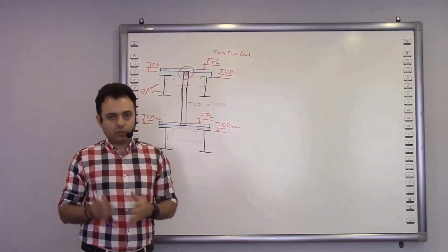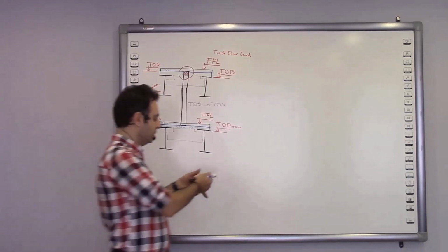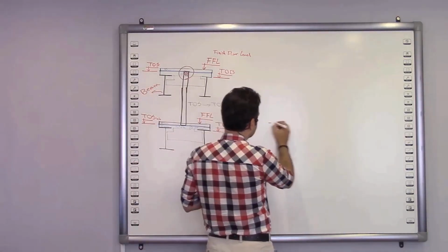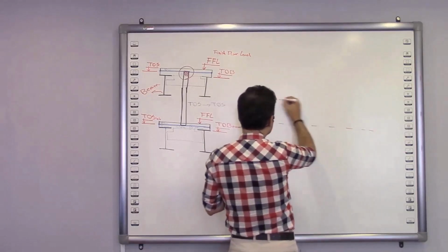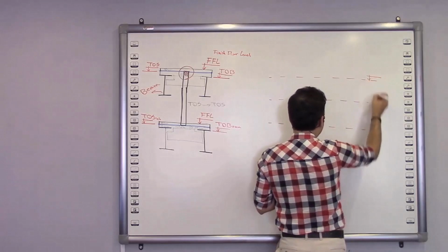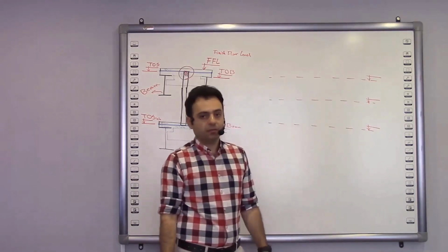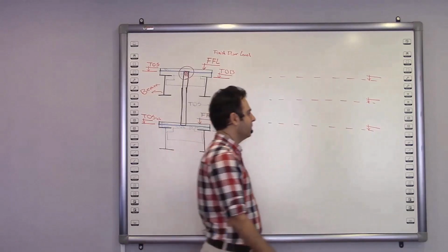Now that you are familiar with the levels and the ceiling system, we need to go and draw these lines in Revit. But just like I said in the first part, we just need TOS. See? So here we have some lines as levels. And we also know that at the beginning of our work, they are TOS. We have nothing to do with FFL for now.